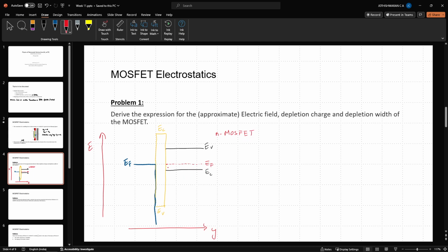The reason why we are considering the conventional metal oxide semiconductor layer is because it is easy to explain inversion and the related phenomena in this model. Now, if we consider a nanoscale device, then I can no longer properly define the conduction and valence band on the channel side, because those are confined systems, as we shall be looking at later.